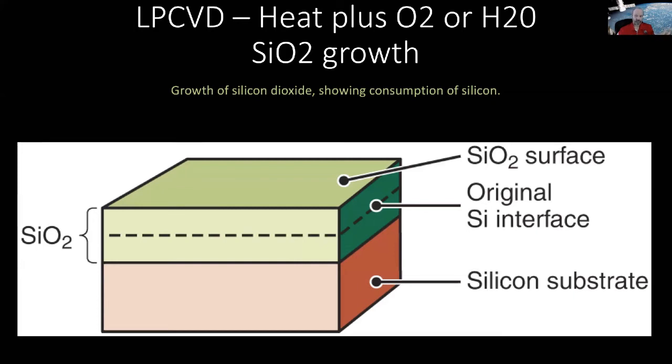Silicon wafers will rust just sitting around, but they stop forming an oxide layer after 1 or 2 or 3 nanometers in thickness of oxide. The reason is the oxygen can no longer get through the formed oxide layer to interact with the silicon substrate. That's called native oxide. Sometimes we strip that off and then put another material on top to get rid of that very thin oxide layer. Even if you leave it out for 10,000 years, it won't get any thicker.